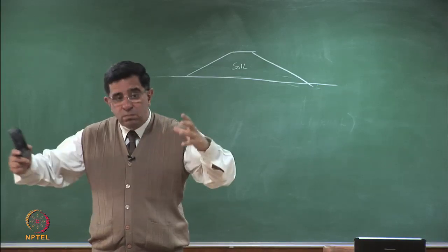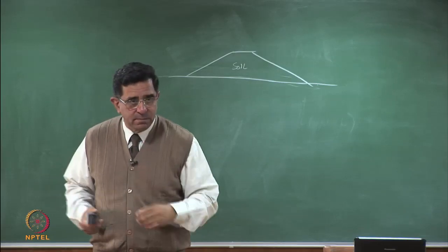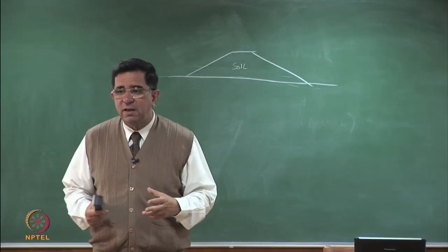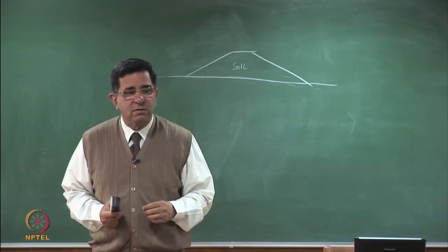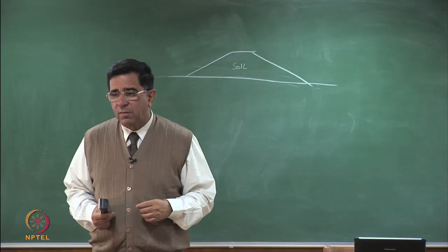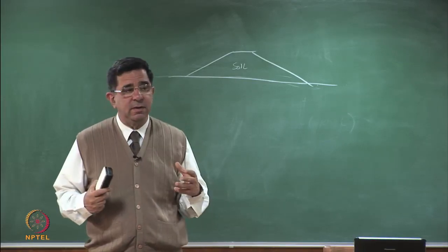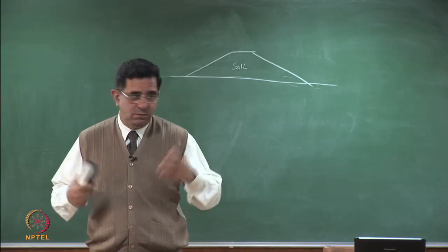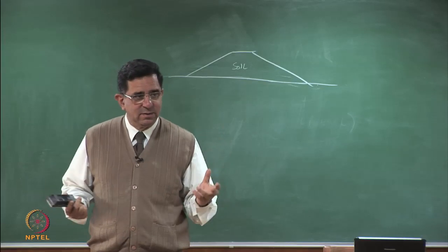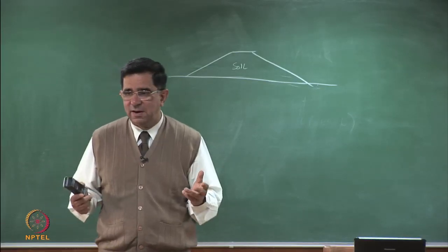If there are huge chunks of construction debris, remove them. Now, what is large size? Anything which is beyond 300 mm, a foot in size. So remove them. And what is the parameter that you will determine? C, phi. C dash, phi dash. There is no other parameter, and if it's a drained test, you're probably getting C dash, phi dash.